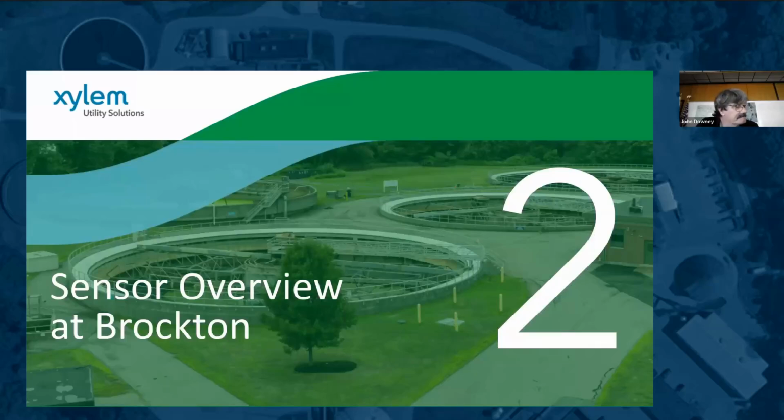Brockton's aeration capability, as Adrienne just laid out, incorporates 7 basins, 4 in the north and 3 on the south side of the plant, fed from 4 primary clarifiers. The north side is fed through 2 flumes, while we feed the south through a primary effluent pump station. And we've got a pump all the way across the plant for that.